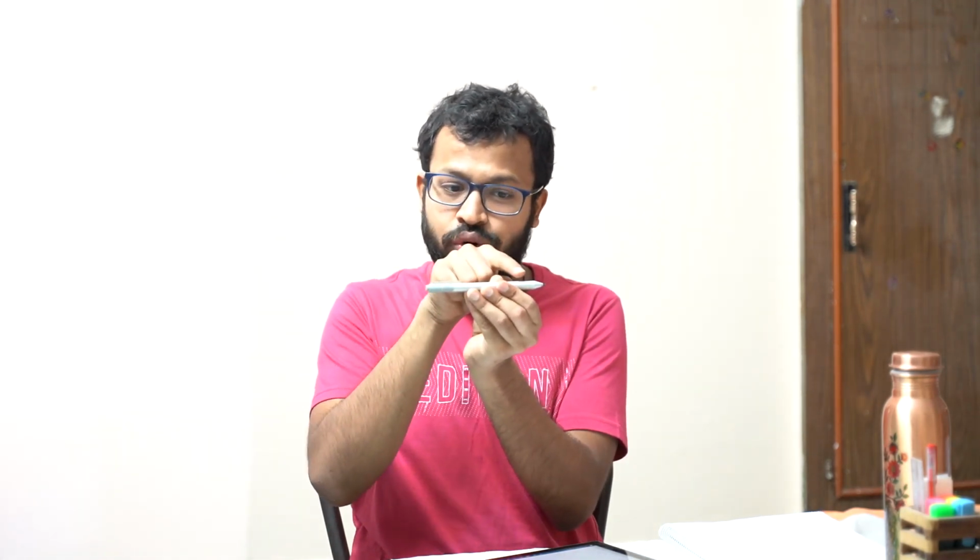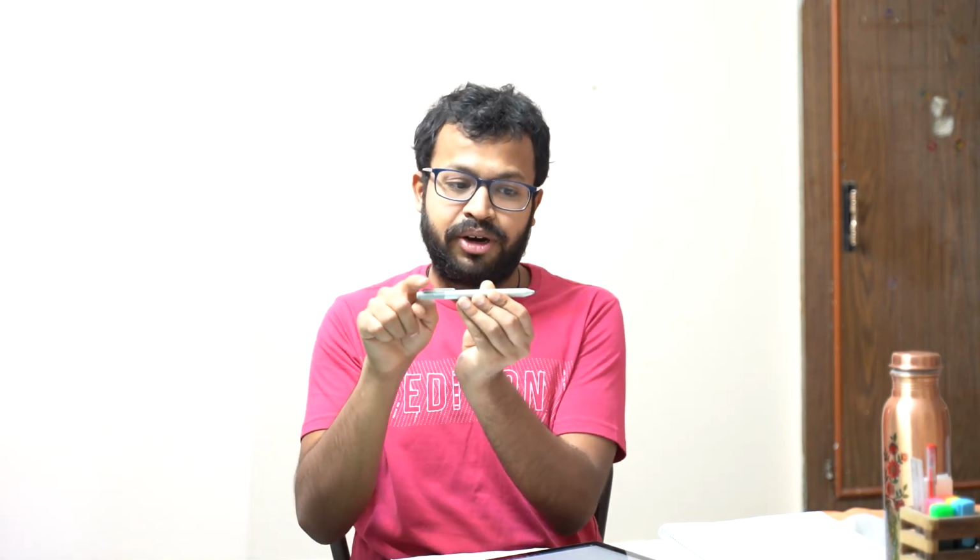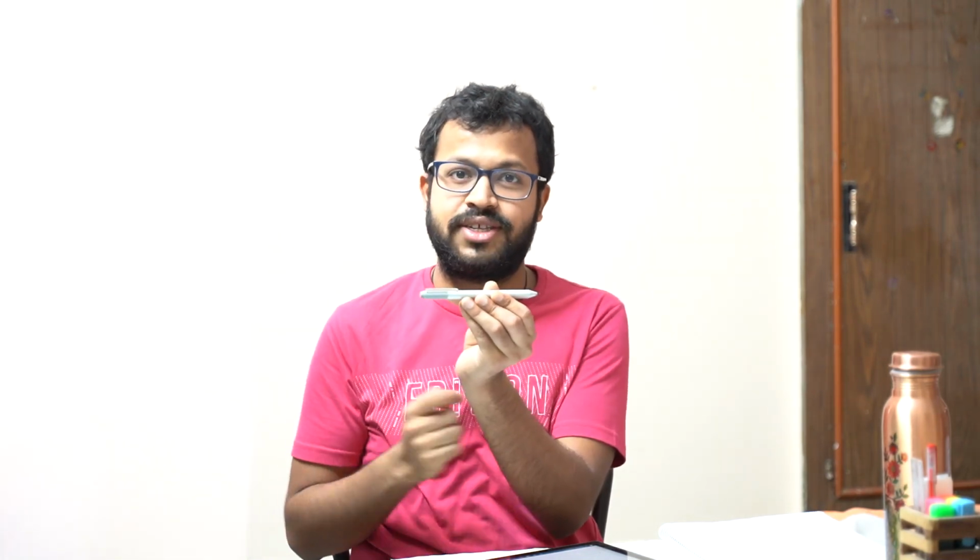The only variable here is the Peclet number, and that determines how quickly or how slowly this change is going to happen. When the Peclet number is very large on the positive side, the variation here would be very slow because it's convecting everything downstream. But as soon as it reaches here, there would be a very sharp gradient across this, right?